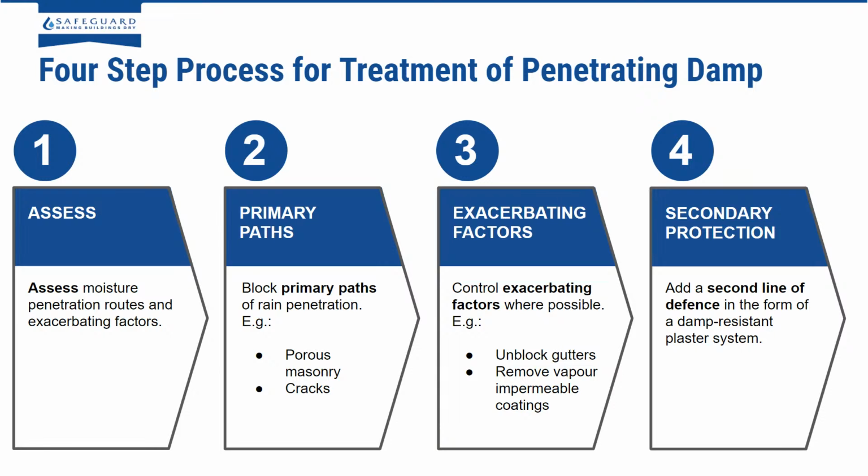Certainly with the more modern renovation plasters, it means that the wall can dry out once it's been treated externally, as an opportunity to evaporate out internally as well. Yeah, so using new modern plasters is usually the best remedy compared to using sand and cement as a way of renovating a property.